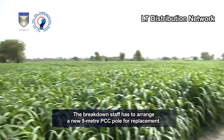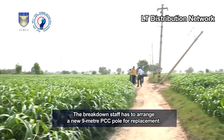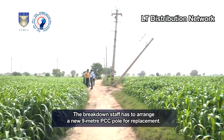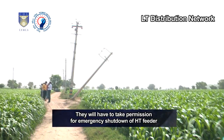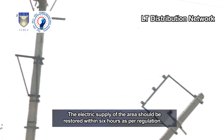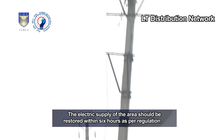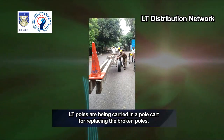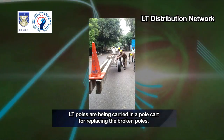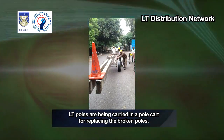The breakdown staff has to arrange a new 9-meter PCC pole for replacement. They will have to take permission for an emergency shutdown of the HT feeder also, as LT lines are leaning over the HT pole, and for erection of the new LT pole. The electric supply of the area should be restored within 6 hours as per regulation. LT poles are being carried in a pole cart for replacing the broken poles.